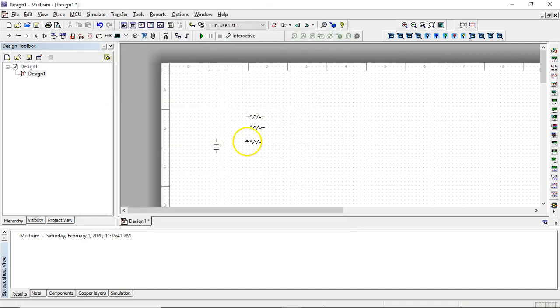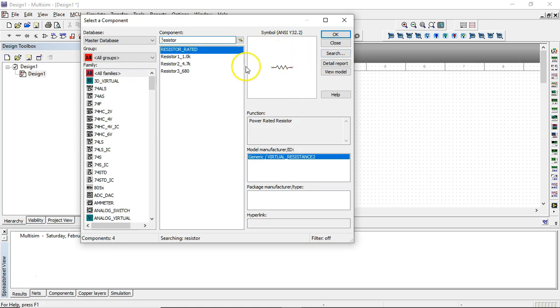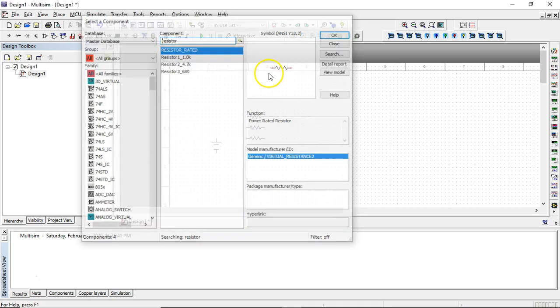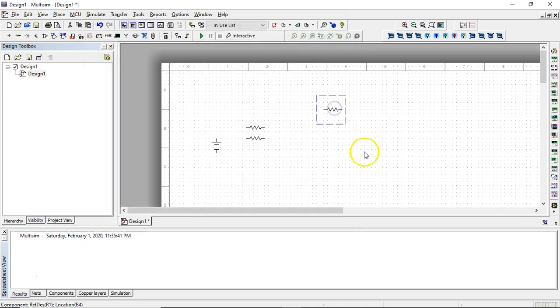You can also copy and paste resistors. However, it will copy and paste the exact value. So if you modified these, it will copy that modified value. Say I placed 1 resistor, say I placed this one here, and I set it to be 13 mega ohms. If I copy and paste it, the other ones will also be 13 mega ohms. But it doesn't really matter as long as I get 3 of them placed.